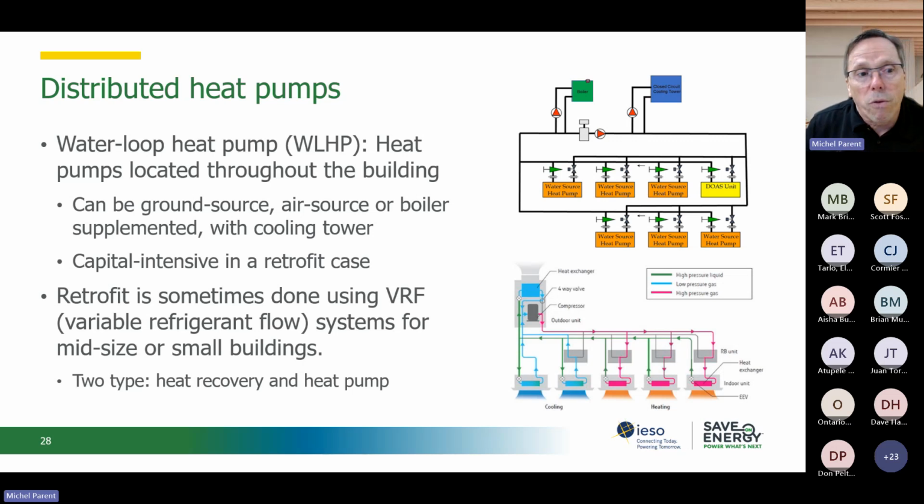The drawback of a VRF unit is that you have a lot of refrigerant. You've got refrigerant line running all over your building. So as the line of refrigerant gets longer, the COP of the system drops. Some people ignore that fact, but as you extend the distribution network of those VRF systems, you can get a significant penalty in your COP, because if you think about it, the compressor, which is outside in this unit, becomes the pump.